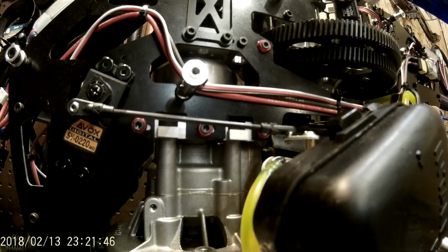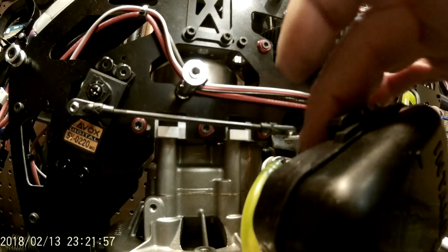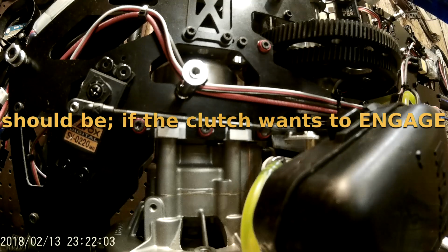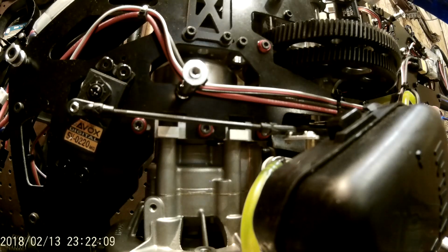When we armed it, the throttle moved to the idle position, and that will allow you to start the engine. And this is where you start it. Hang on to the head, start the engine. If it's idling too high and the clutch wants to disengage, make sure you have your RC radio handy, and hang on to that head. Don't let it turn and get tangled up in your starter wand if you have a top start system.